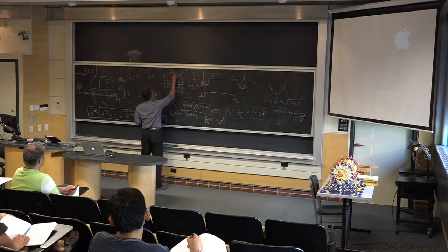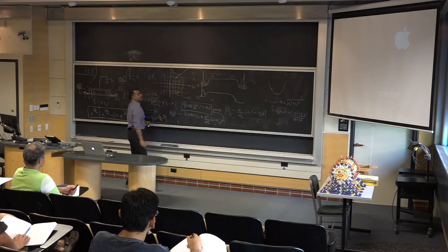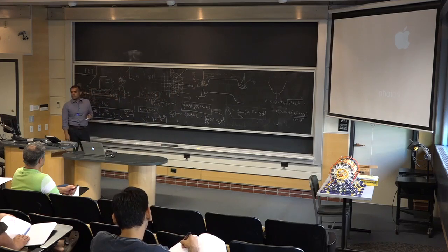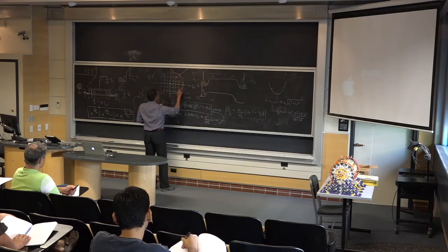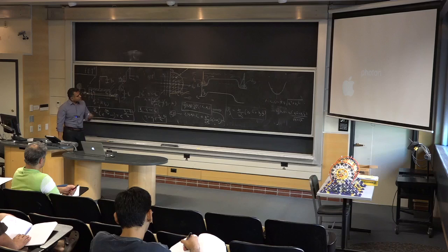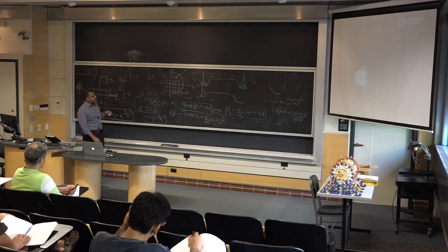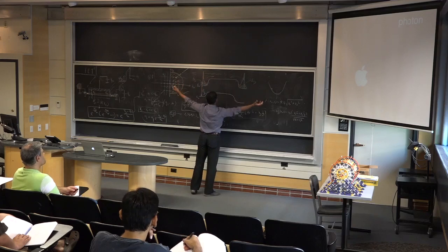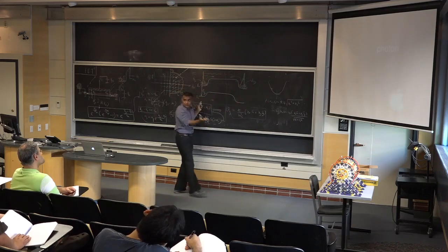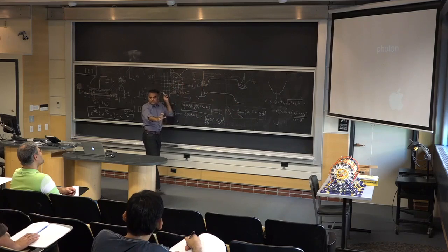All these modes are filled by the source. Does that make sense? All the ones I colored with this orange, all those modes are filled by the source. And how much is the filling? Whenever we say how many states are filled, you always have to look for one number, and that is the Fermi level. But here you see there are two different baths. One is doing its job, the other is doing its job. They could be independent. Right now we're saying they're the same. The moment you apply drain voltage, they become independent of each other.